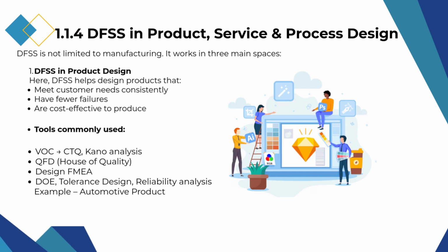DFSS is not limited to manufacturing and is equally effective in product, service, and process design. In product design, it is used to create products that consistently meet customer needs, have fewer failures, and are cost-effective to produce by applying tools such as voice of customer to CTQ translation, Kano analysis, QFD or house of quality, design FMEA, and techniques like DOE, tolerance design, and reliability analysis, as commonly seen in automotive product development.